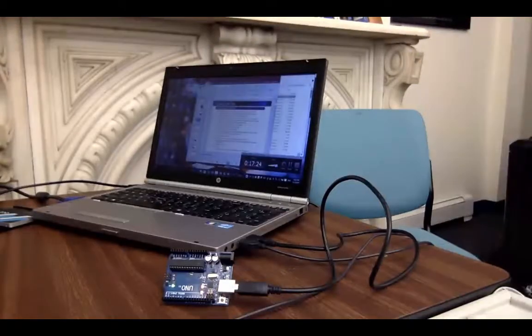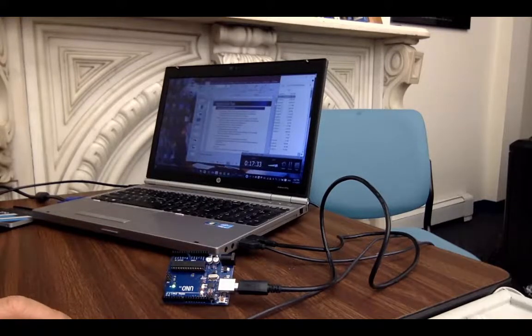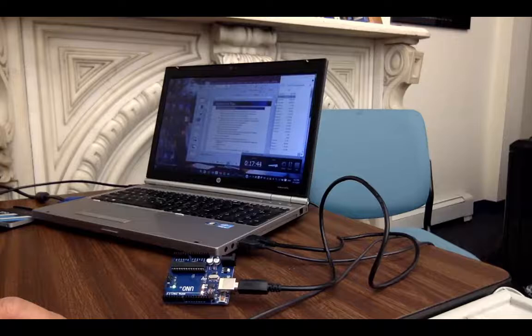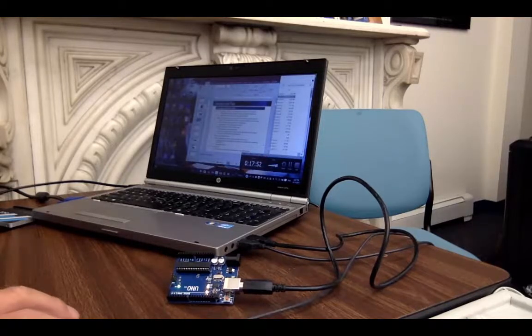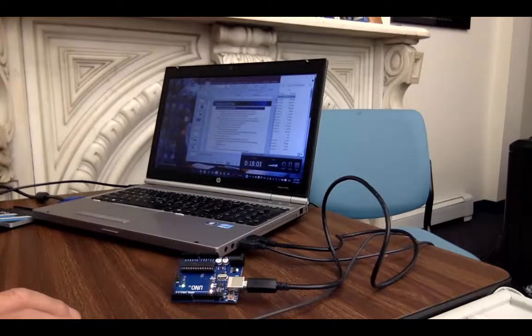All right, so I wanted to make sure that you have that board and port. COM port 1 usually is not for your Arduino Uno, but you have to find out if there is another COM port. It says Arduino or Genuino Uno with the COM port label, then click on it. So that when you come back here to tools, you see there is a board, there is a port. Make sure those two elements are filled in. Okay? All right, then